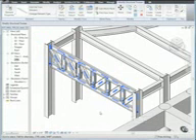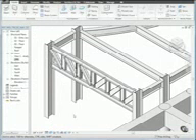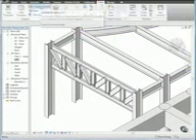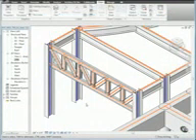Clear the selection, and let's view the truss analytical model. Click the View tab on the ribbon, and on the Graphics panel, click Visibility Graphics. Then, on the Model Categories tab, under Visibility, expand Structural Framing and select Analytical Model. Then expand Structural Columns and click Analytical Model and click OK. The orange lines represent the analytical model of the truss.